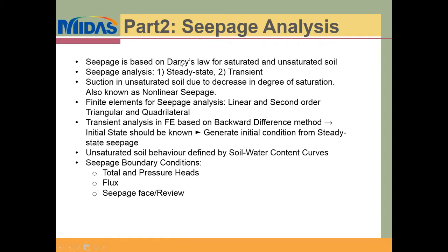It is based on Darcy's law for saturated and unsaturated soil. For the unsaturated soil, the Darcy law is modified, and the analysis can be performed both for the steady state and the transient state. And sometimes your soil might not be fully saturated. In that case, the unsaturated behavior in the soil invokes the requirement of the nonlinear seepage.